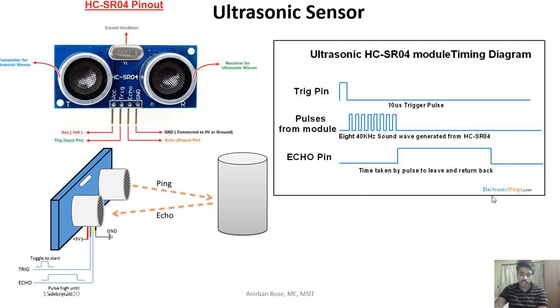Another one you see is the ultrasonic sensor, where the principle is that one of them will send ultrasonic sound, and after triggering that, if some object is there, it will reflect it, and that reflection is collected, and accordingly it is possible to identify the distance of the object. Not only whether the object is present or not, it is possible to identify how far away it is with the help of the ultrasonic sensor.